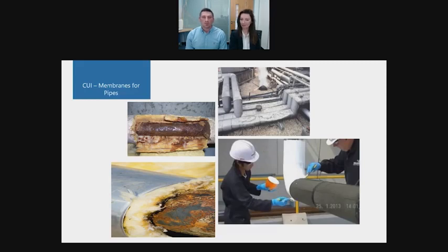The microporous properties mean that it's ideal for applying to insulation. It allows any moisture from underneath and inside the insulation to escape, but at the same time prevents any water penetrating through. The membrane can also be cut to create a hole for inspection purposes, and then resealed with an additional layer of membrane.